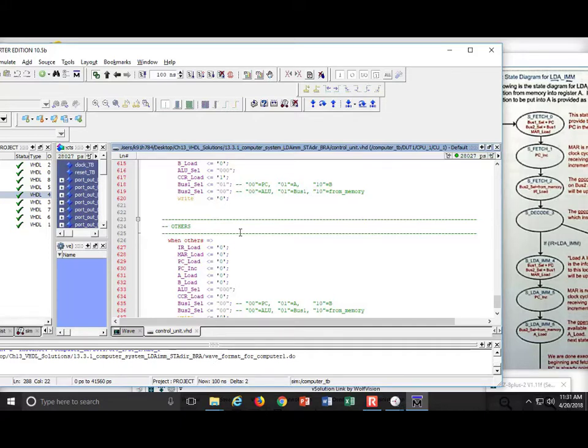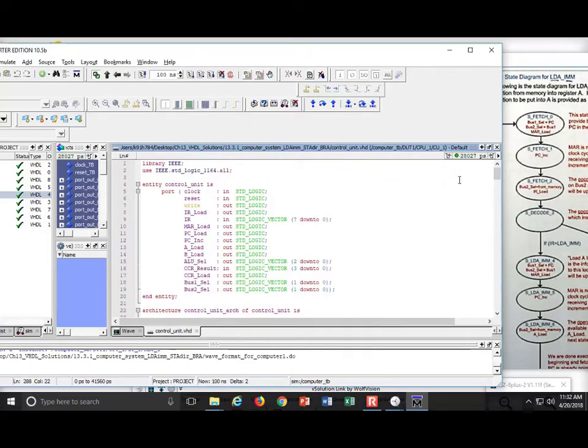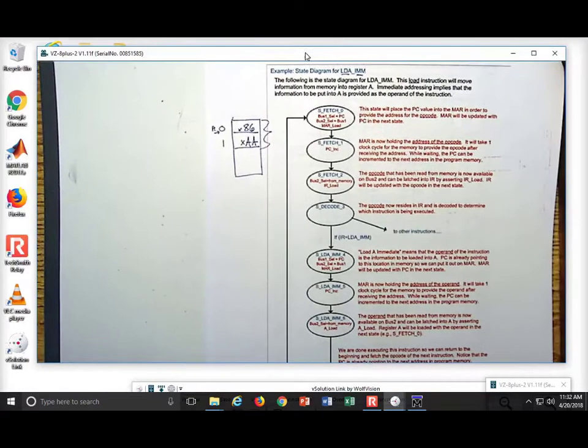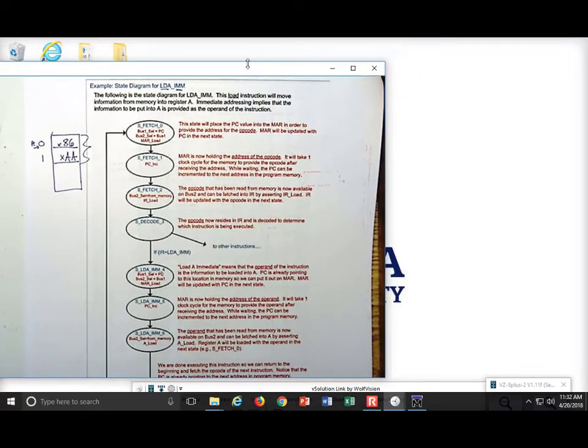But it can be quite intimidating and overwhelming if you don't comment it. So what I do is I try to make these comment basically dividers. That's why you don't do it all at once. Don't paste in every output logic for every state that you think is going to be in the computer. Get one instruction working, then move to the next one. That's the way you can debug and move on to the next. Okay, this feels phenomenal. I know how to code the VHDL. Now let's just go through why we are actually moving these states the way that I am moving them.